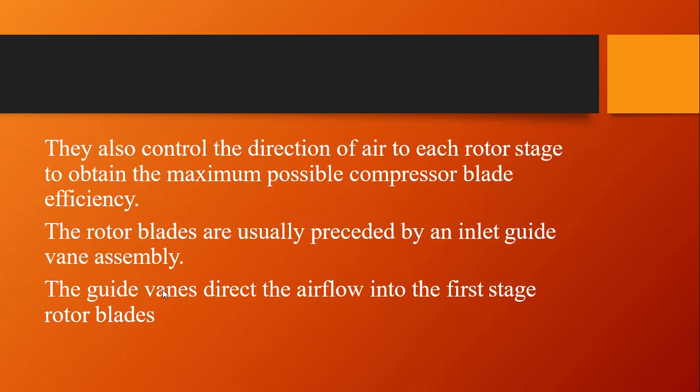They also control the direction of air to each rotor stage to obtain maximum possible compressor blade efficiency. The rotor blades are usually preceded by an inlet guide vane assembly.